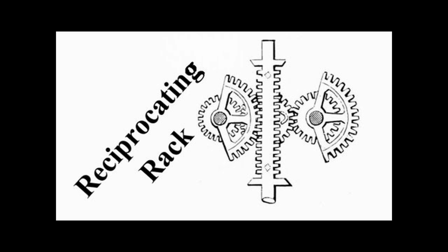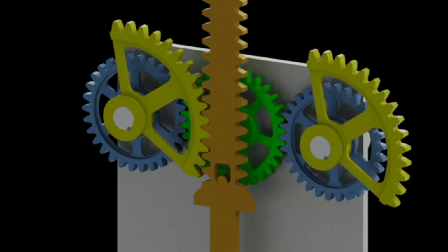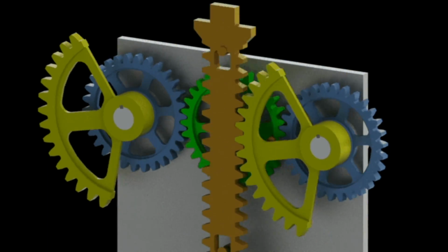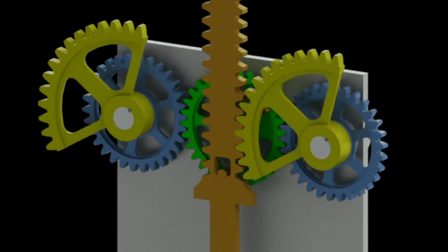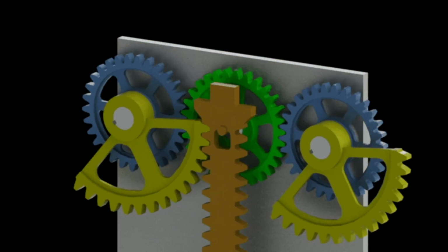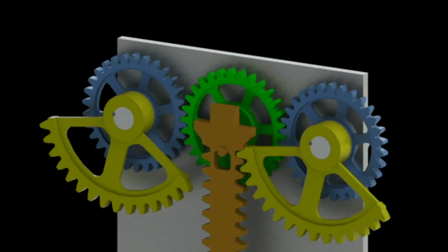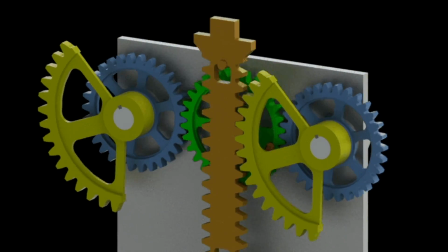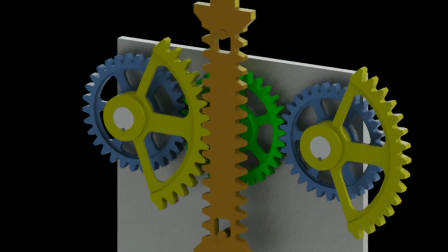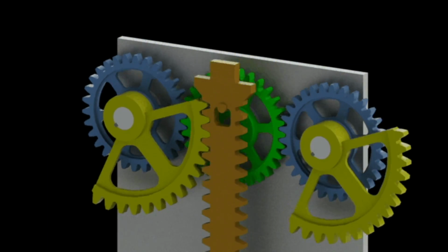We tried to mimic movement 123, which is a reciprocating rack mechanism. The rack was attached to the piston and moved up and down. The rack itself engaged with 2 half pinion gears. The half gears were interfaced with smaller gears that turned the middle gear. The middle gear only turned in one direction because of the mechanism, so the weight attached to it would only rise. The pinion gear moved clockwise from the down to up position, which turned the middle gear counterclockwise.